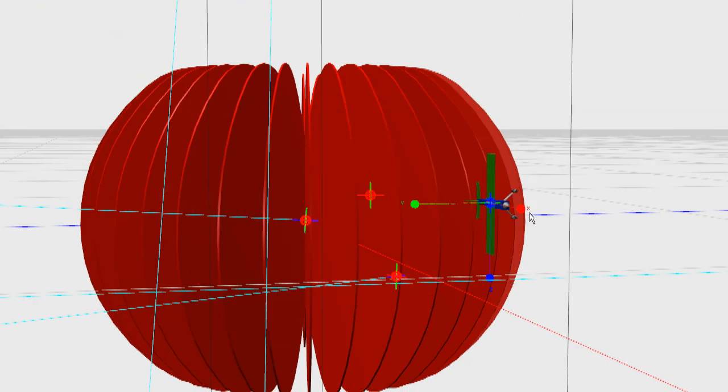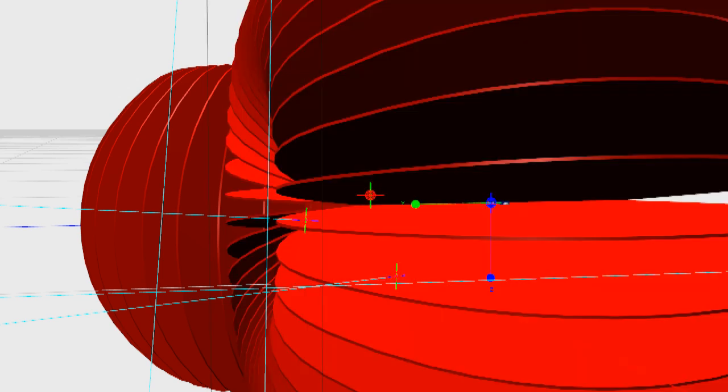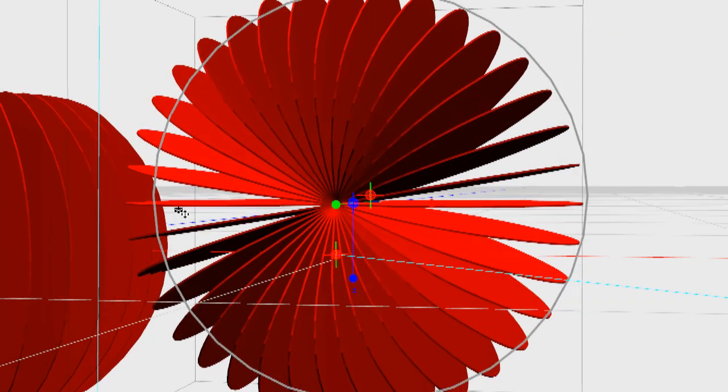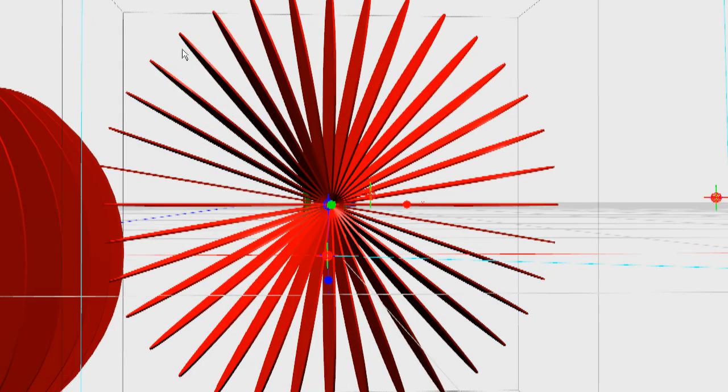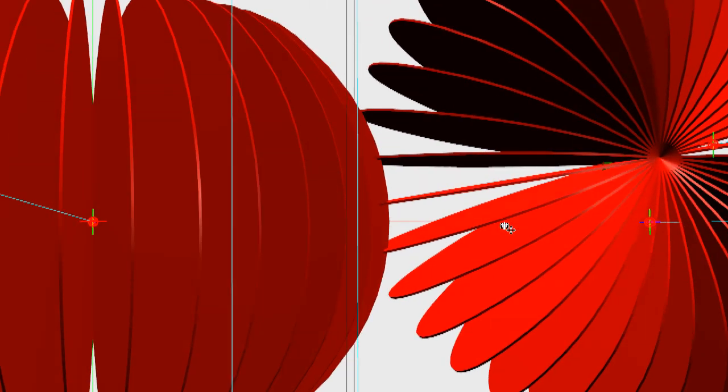Now, as a result of that, so is our signal. Regardless, we'll switch back to the front view. There's our plane in a hard turn. Now, just because our plane is in range doesn't mean we're going to get a good signal, because we've got a mismatch of polarization here. One is vertically polarized, the ground station, but the plane is now horizontally polarized. So what it means is that we have a mismatch of polarization.